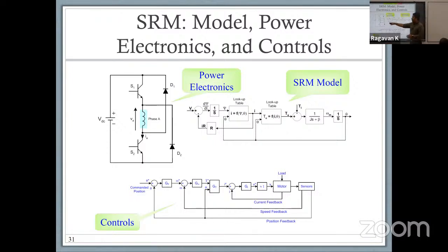This topology, if you break it down, looks fancy. It's an asymmetric bridge, but it's the same idea as the full bridge, but instead of the switches, we have a switch here; flip the inductor and you will get a diode and inductor. So it looks very much like a conventional bridge rectifier with two switches and two diodes. It just looks fancy because we have connected the points at a funny angle, right?